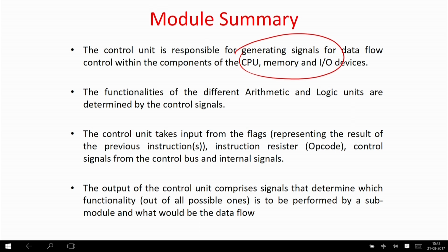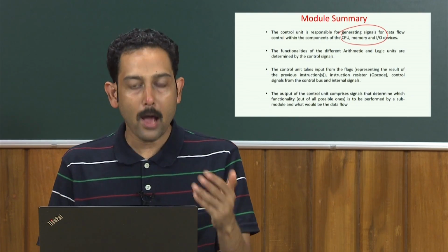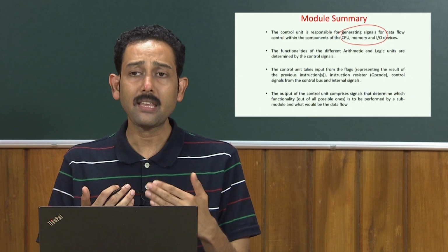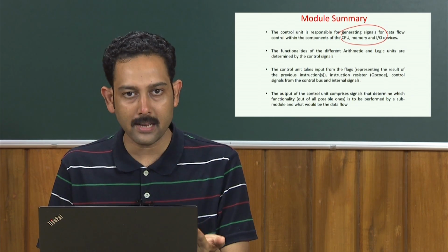When the data has been given to the memory buffer register from the memory, you should generate a signal saying that the data is now ready and has been sent to the buffer, so you can read it. For example, if you want to write something to the memory, you write it into the memory buffer register and then you have to wait for some time. All these are handshaking signals. For example, if the 0 flag is set, that means a control signal will be generated.